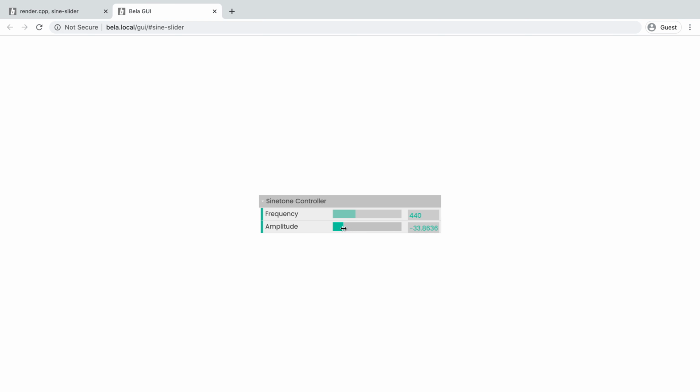Now you might hear some clicks here. Sort of zipper noise as we increase and decrease the slider. Where does that come from? We'll look at that kind of thing later on, but this has to do with the value of the amplitude suddenly jumping between one call to render and the next, which leads to a discontinuity in the signal.